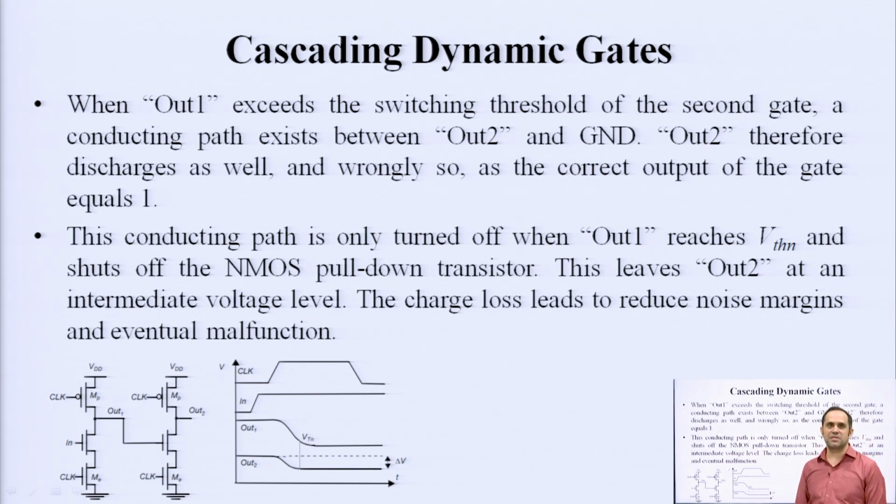So, this is a major problem which does not happen in static CMOS circuits, because their data is held as long as your power is on. So, there is a lot of time which can cover the propagation delays. So, data integrity is not affected, but in dynamic CMOS circuits, because of this continuous charging, discharging and the finite time it takes to do that, simple cascading will definitely cause loss of charge, loss of valuable data, which again cannot be retrieved within the evaluation cycle. Okay.